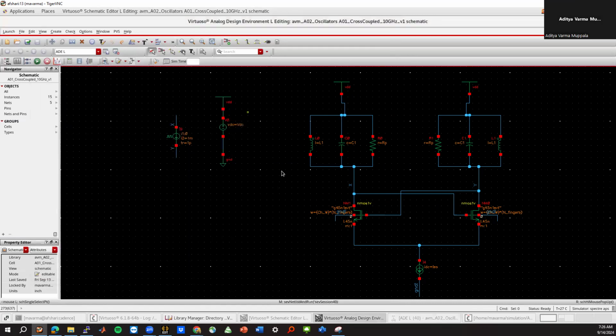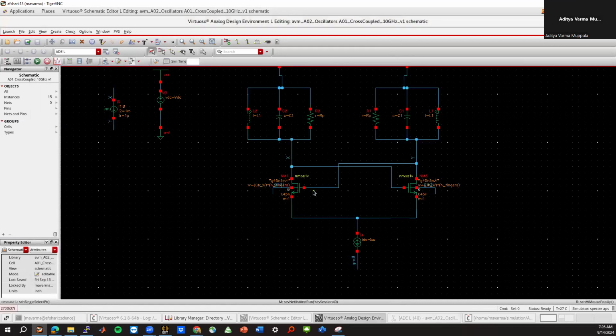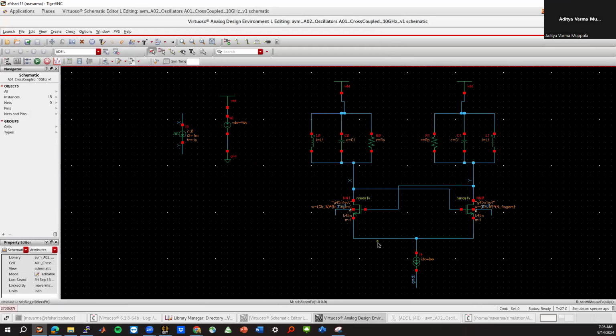All right, so that pretty much concludes what we have done here. In the next video, I would like to look at how to make this more realistic using current mirrors and how to design the current mirror correctly. And then we'll also make this realistic. We'll probably do the layout for these transistors and combine all of this into one oscillator that is actually more realistic at 10 gigahertz. Once we finish all that at 10 gigahertz, then we'll move on to doing a millimeter wave, let's say 100 gigahertz oscillator, right? And we'll see where to go from there. I'll also show you how to simulate the ISF function using an impulse current source. So the time domain ISF simulation for both stationary and cyclostationary noise sources.